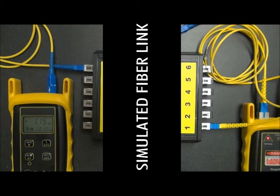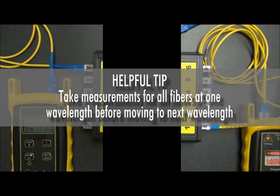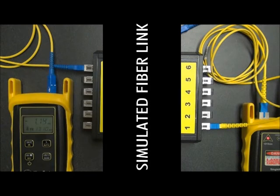Now, one helpful tip that I'd like to cover before I continue is that the best way of taking dual wavelength measurements with this particular test kit is to store all the readings at one wavelength first, then store the 6 readings at the other wavelength after that. The reason is that you don't have to keep pressing a wavelength button, switching back and forth from port to port. Simply test all the ports at one wavelength. Then you only have to change the wavelength once on both units. So I'm going to speed up the process here and store all 6 readings.